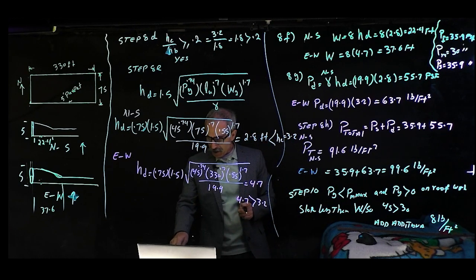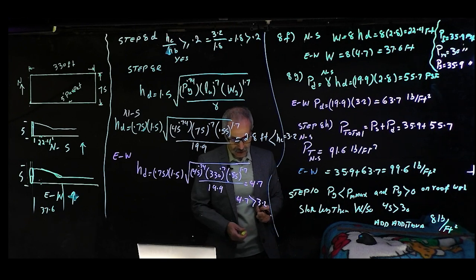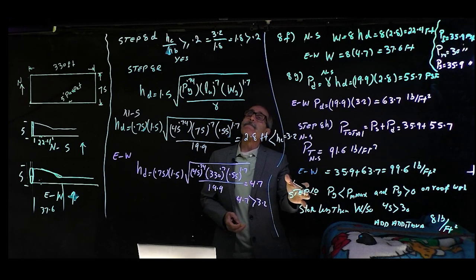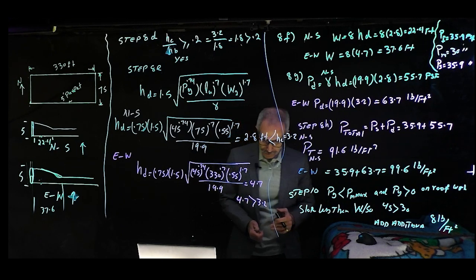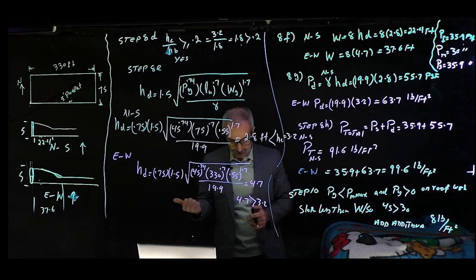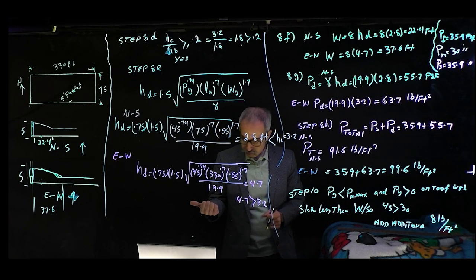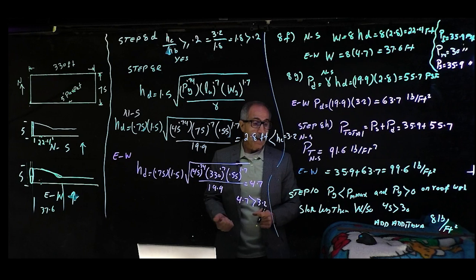It says consider ponding instability. That's something you really should do some analysis on if you're going to have a deflection. We did that in rain load. See if you have ponding. If you don't have it, you don't have an issue. So go back to that, and then consider existing roof, which doesn't apply, and 13, consider snow load on an open frame. That doesn't apply, and that's it.